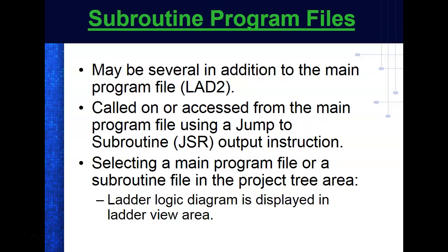Instead of me trying to find the section of that program that taught it how to pick the block up, I just found the subroutine that does that. So I was able to teach, and I could loop those subroutines, and I could reteach the points until everything was right. So writing structured programs is something that you really, really need to learn.